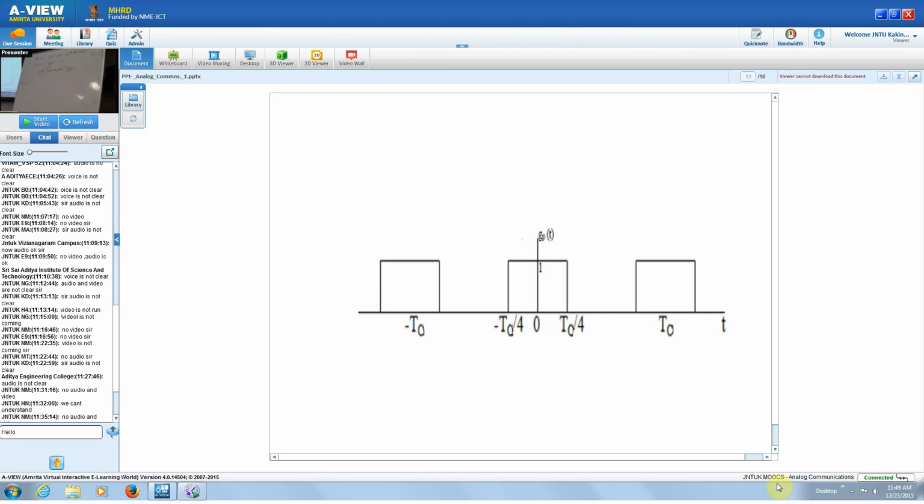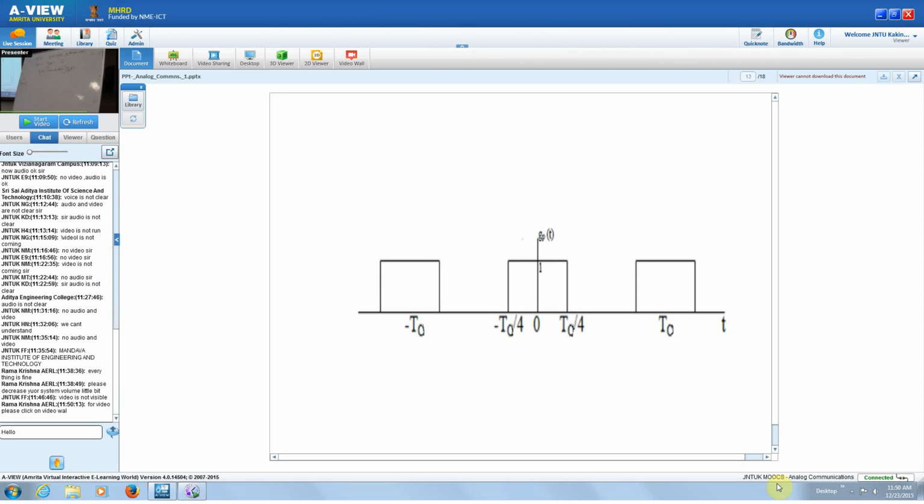So this is the pulse signal that we are going to have, g_p(t). I am multiplying this m(t) into A_c cos omega_c t with this pulse on and off period, with equal on and off periods, because c(t) is positive or negative in the cos omega_c t, the carrier signal, for equal periods. So you are having an equal rectangular periodic signal.